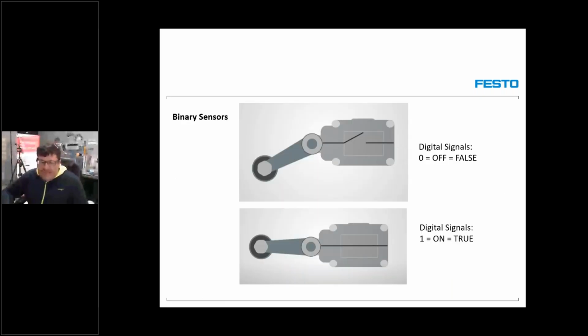Right, now I've mentioned the binary sensors to you, guys. Binary sensors like a proximity sensor or a limit switch are what we refer to as a digital signal. In our case, the power that we wired onto my limit switch will be 24 volt. Remember, this limit switch for the garage door, for example, is represented as a switch. It's a normally open switch. That means currently the voltage being sent is 0 volt, so it will be 0, it will be off, or it will be false.